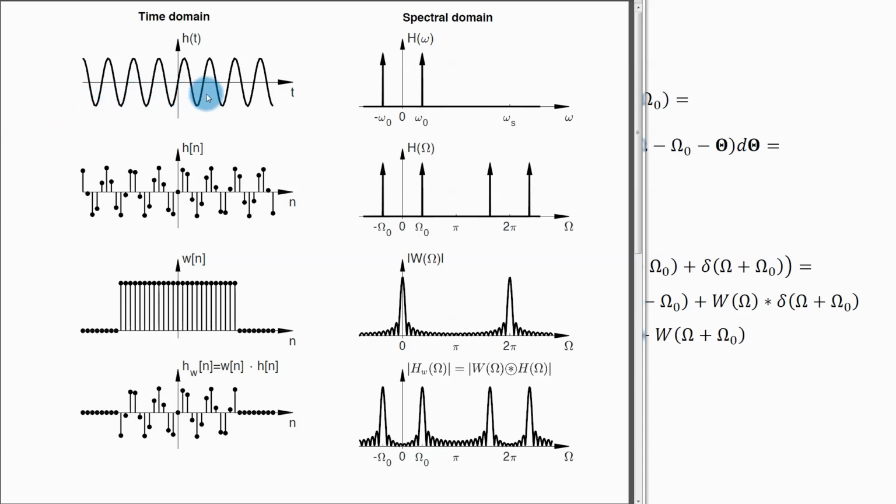Here I have a very simple example where I have a sine function and I would like to compute its spectrum. I will start with a trivial but rather unrealistic case where this sine is continuous in time. On the exercise I showed you that the spectrum of the sine function are two Dirac delta pulses. The sine wave is a pure tone, so in the spectrum all its energy is on a single frequency. And if anybody shows me this spectrum, I have no problem reading it as a spectrum of a sine.